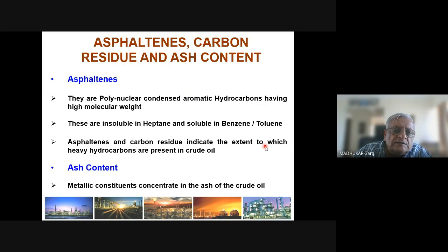Coming to the other characteristics of crude oil, asphaltenes are very important, because asphaltenes are something on which you can't really do any value addition. If you have to add value to asphaltenes to convert them back to gasoline and diesel, a large amount of hydrogen and energy is required. So if you have a higher asphaltene content in crude oil, to that extent the crude oil has lesser value for you in terms of making profit.